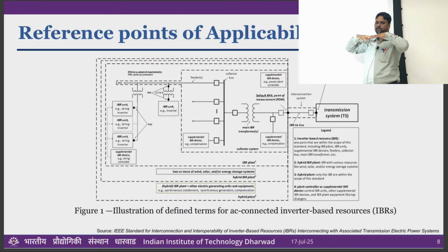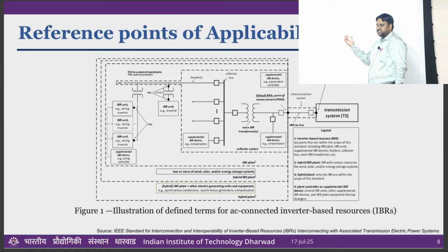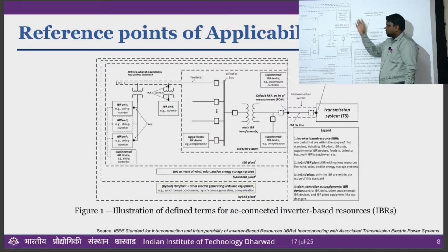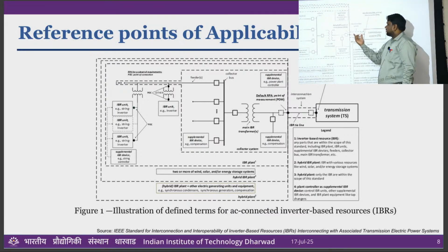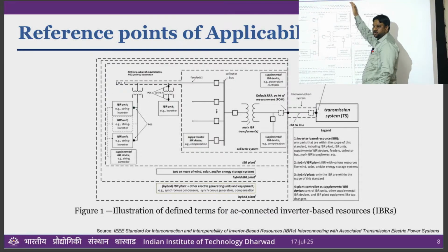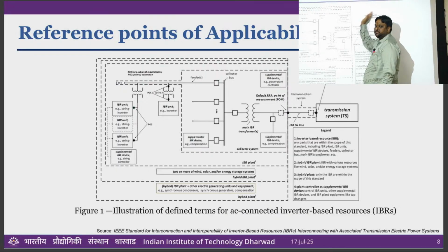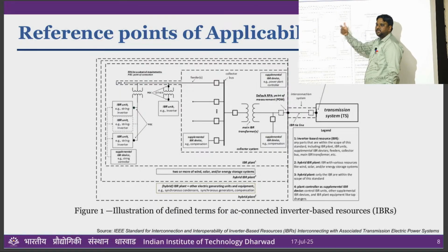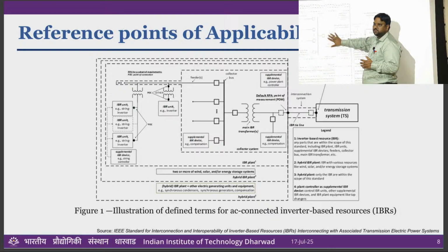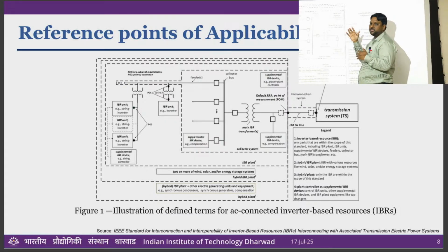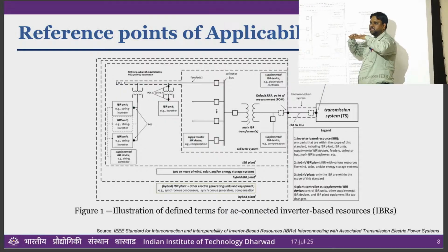All this measurement goes to that layer of control, the PPC, where forecasting, optimization and demand response happen. Then new P and Q are generated based on optimization, deciding how much this unit has to inject after doing the generation-demand balance at the tertiary level.